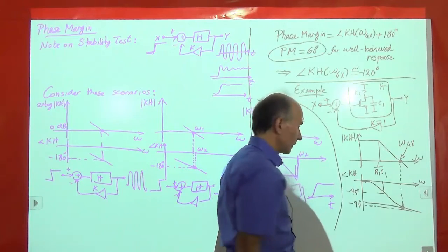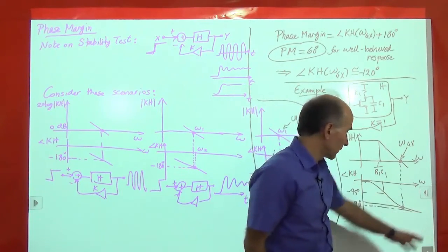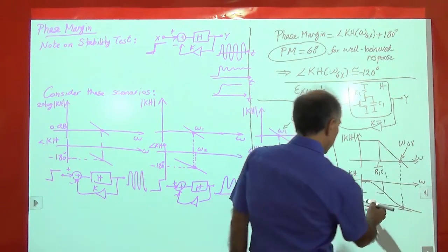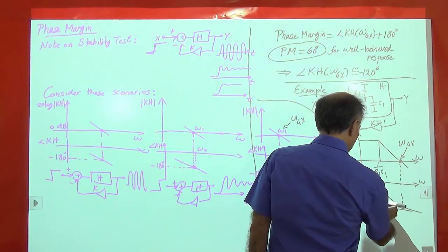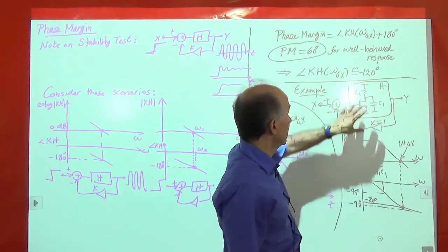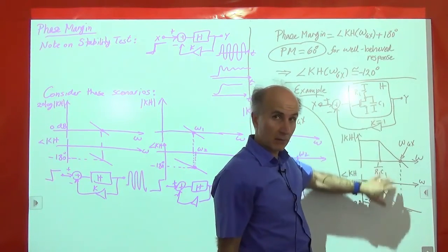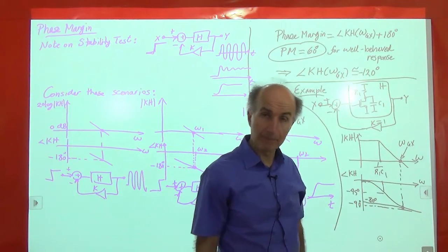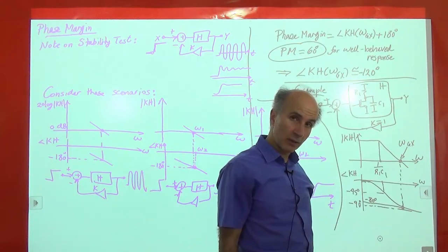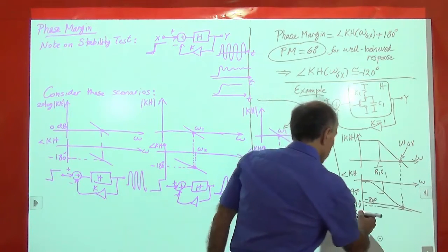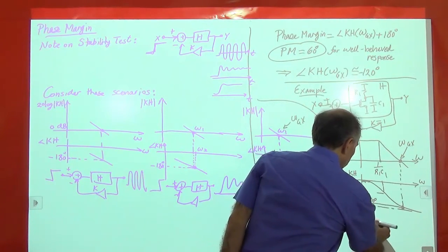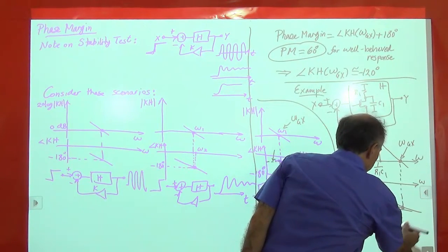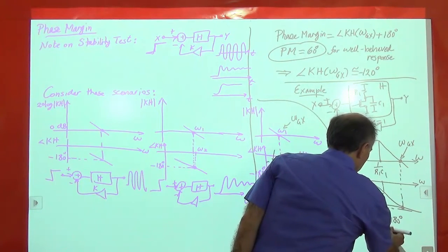It's not minus 90, because minus 90 would be at infinite frequency. It's some amount, right? We can calculate that. So let's say it's minus 80 degrees as an example, right? It's not that hard, right? Because we have the equation for this transfer function. You can readily find that. But if it's minus 80, as an example, what is the phase margin? Okay, so if that's, then the phase margin would be minus 80 degrees plus 180 degrees. So it's 100 degrees of phase margin, right?